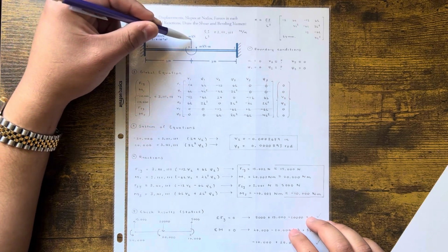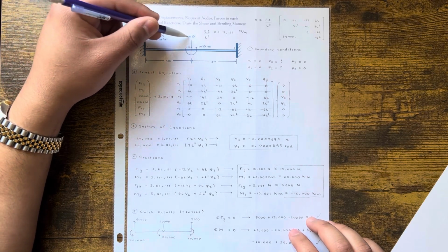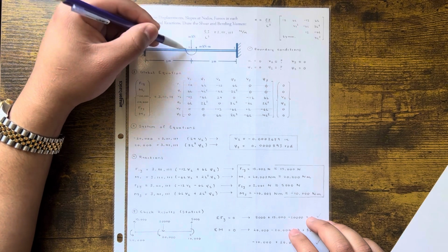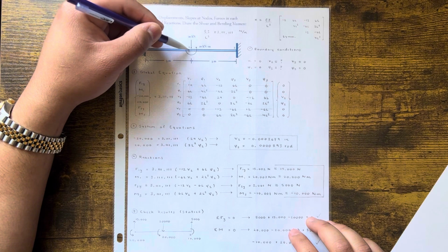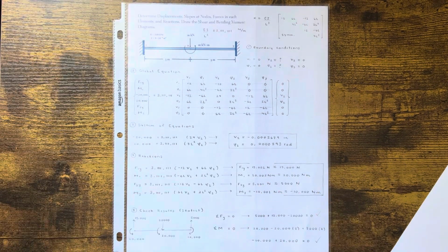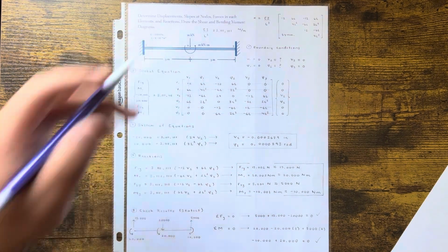So you have to design, in this case, they already designed it actually. They designed a cross section for that wing saying, hey, 20,000, and there's probably a moment acting on it. Can my beam support it? What's my displacement looking like? What's my angle looking like? The slopes, right? And these are kind of just checks.